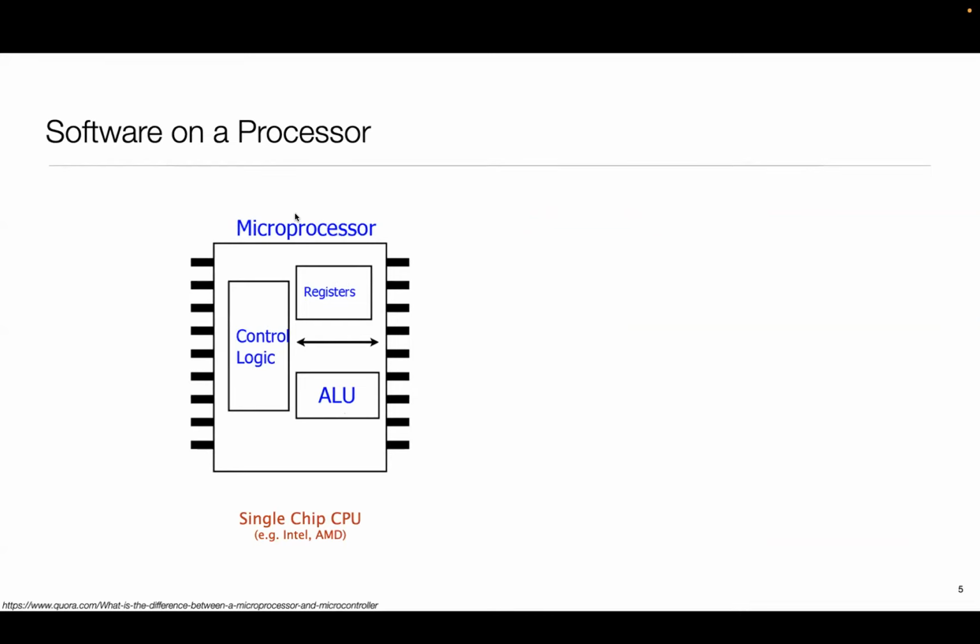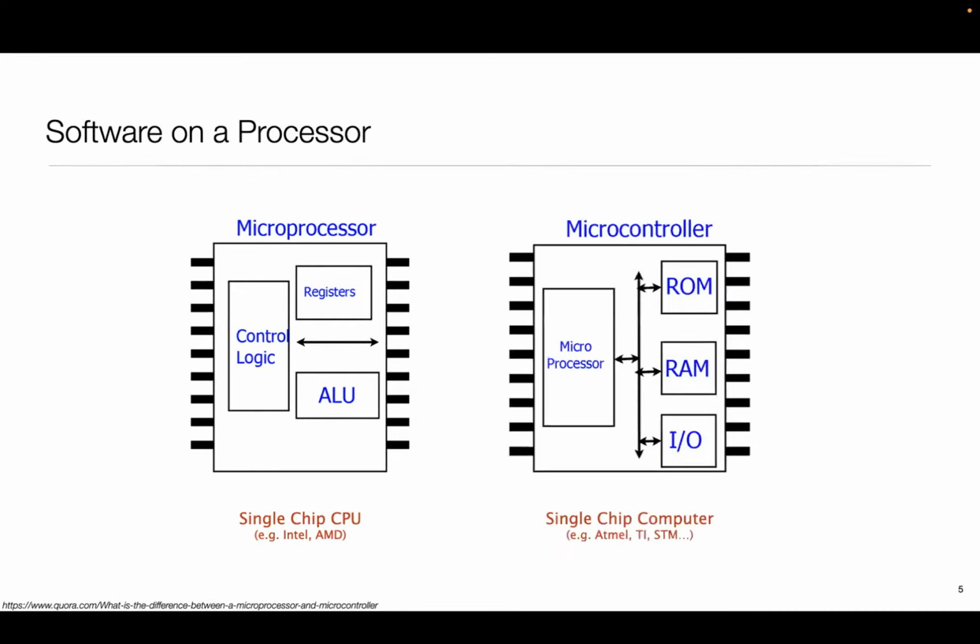There are versions of microprocessor where in the same mechanical package, we also slap in memory. So some DRAM, some SRAM, all sitting together. In fact, one of the reasons Apple made a big splash with these M processors is that they put the processor together with the memory all into the same package, and then they are able to put a large amount of memory, which both the ALU, whatever the processor, can access, and which the GPU on these laptops can access. So some big advantages there. So packaging these things plays a huge role.